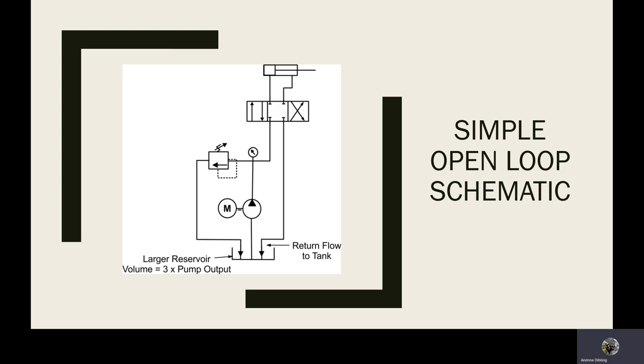A lot of times you'll get dirt inside a fitting. In one instance, we had food processing equipment that was all linked together hydraulically. So when you put another conveyor on, you simply added another power pack and connected the lines to the header. However, because of dirt and the environment, eventually you'd get enough mud in the lines that it would start to affect pressure, speed and flow down the line, and your pressure relief valves would start going off at your main pump. So these are all signs, from being in the field, of what happens when.